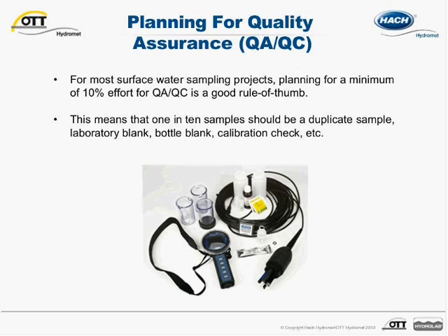At 15-minute intervals, which is about 100 measurements per day, it would defeat the purpose of having a deployed instrument and also get 10 QA/QC measurements per day to meet the 10% guideline. The best that can be done from a practical standpoint is to take QA/QC measurements or samples at the beginning and end of each data set. Assuming a typical deployment of 30 days, 3,000 meter readings would be collected during this period, with only 2 QA/QC measurements. This is less than 0.1% effort put into QA/QC, far short of the 10% rule, but may be the best that one can do.